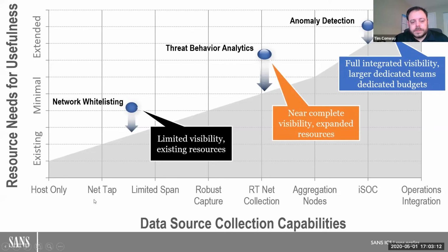to do some level of analysis and some level of detection. Over time, system vendors and the network infrastructure within these deployments gained the ability to have network tap capability and limited port spanning within some of the industrial switches, where you could pick 1 or 2 ports that you were going to monitor and that was it, without making the original equipment manufacturer nervous that you were overloading the backplane and you may miss a scan or miss an important operational data transfer that could potentially cause some issues with the equipment from a safety or reliability event.